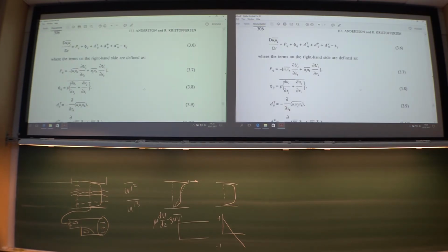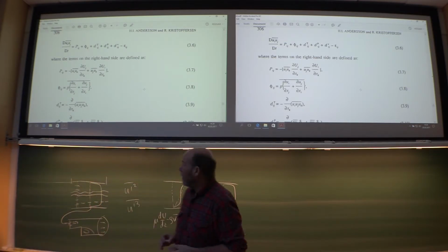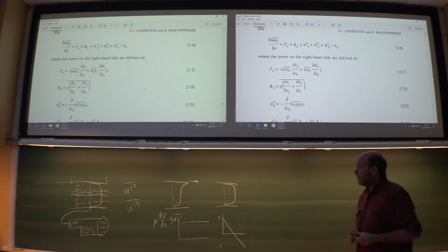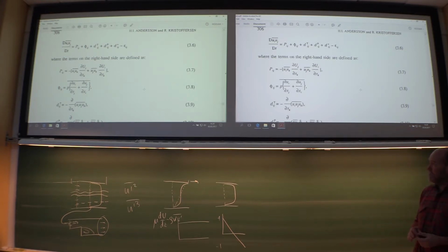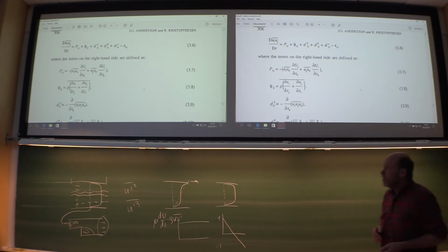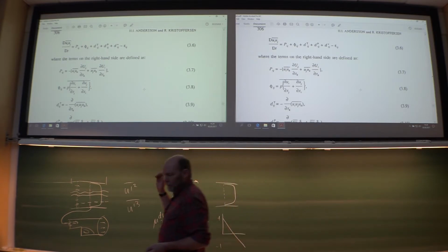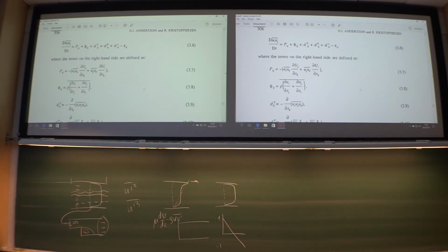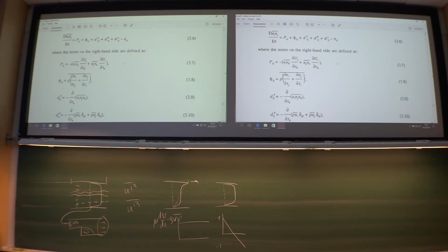For the turbulence modelers, people who are creating turbulence models, they were really happy when we started doing DNS and could provide them with actual numbers. How do these functions actually look? Remember, for a full Reynolds stress model, if you can recall, the transport equation for all of the different Reynolds stresses, it was only the production term, this one, that was exact.